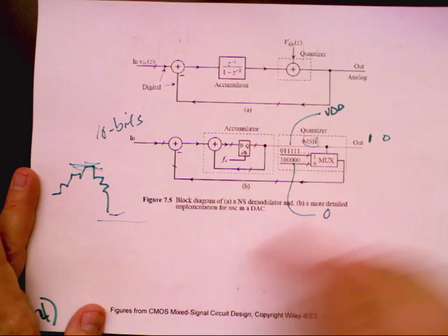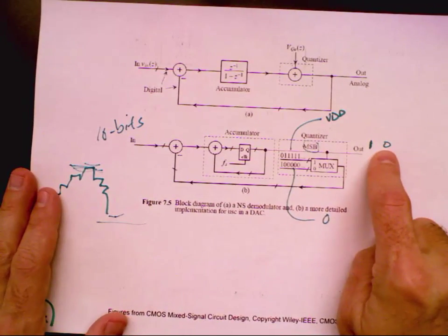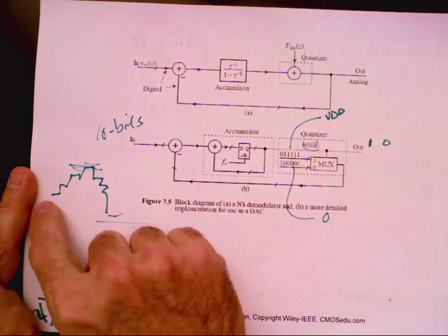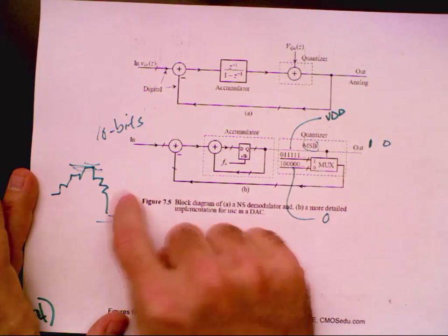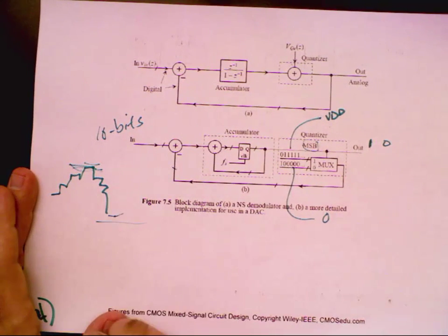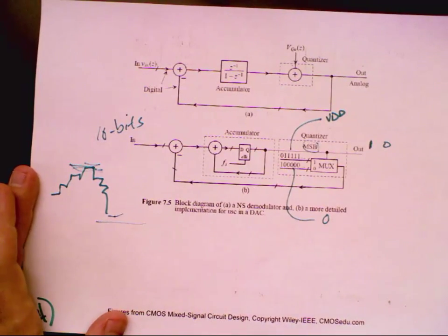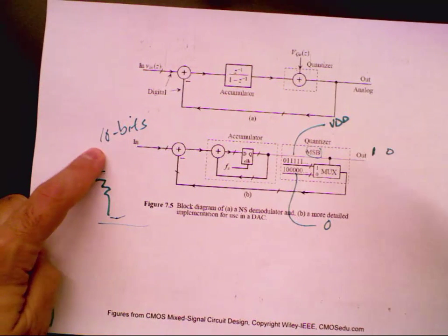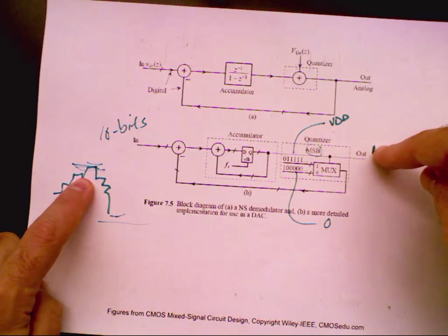And the benefit here is that I take this digital 10-bit waveform and I represent it as a 1-bit code that comes out at a lot faster rate. The benefit of the analog is I got an analog signal and I get a 1-bit code that comes out digital. Here I'm saying digital on both ends, but my bit stream comes out very fast relative to this one. Any questions? I'm assuming everybody can make the transition. 1 bit, easy to transmit. 10 bits, less easy. To keep the information, I got to go faster here. This has to be slower, so I get oversampling.